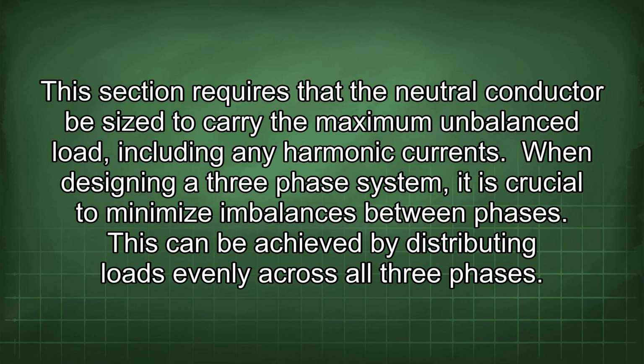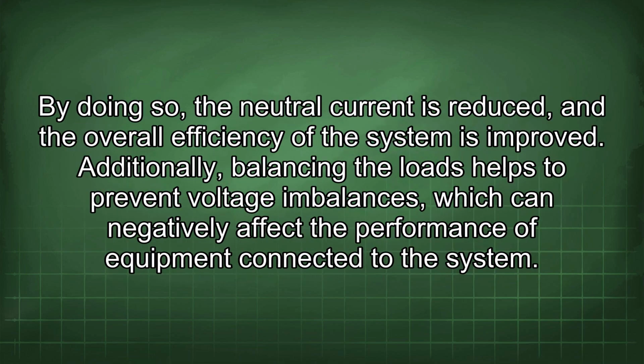When designing a three-phase system, it is crucial to minimize imbalances between phases. This can be achieved by distributing loads evenly across all three phases. By doing so, the neutral current is reduced, and the overall efficiency of the system is improved.